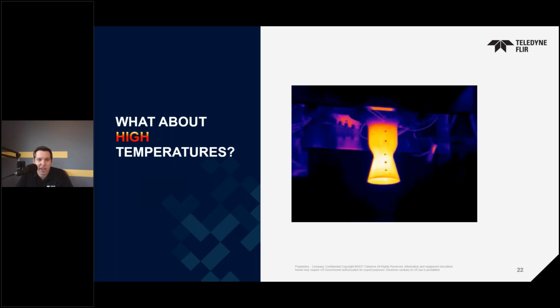Due to the location of a hotspot, that researcher can then identify what's co-located with the hotspot and determine the potential cause of any issues on that rocket body. As long as there aren't other requirements that would mark the cooled photon counter as the more appropriate option, let's say high-speed events, let's say wanting to measure transient thermal events, tight synchronization with other instrumentation, specific wavebands of interest, those kind of things, the bolometer could certainly be a good option for hot scenes.